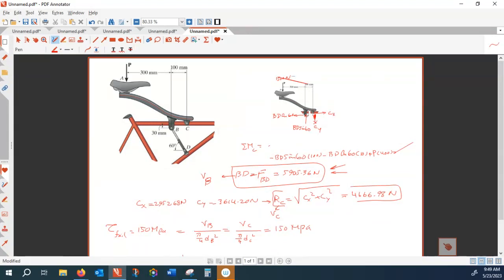And with that, I'm assuming the pins are single shear. You know the difference between single shear and double shear? So double shear, the shear force develops over two areas. So here, that is a single shear. I mean, you could have made this double shear to become stronger. Double shear requires two tongues and one pin. But if that's one tongue, one pin, that's single shear.